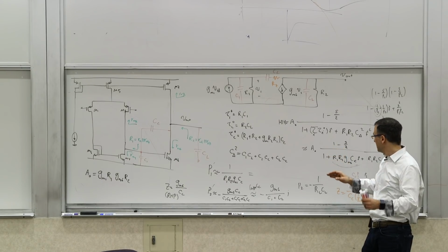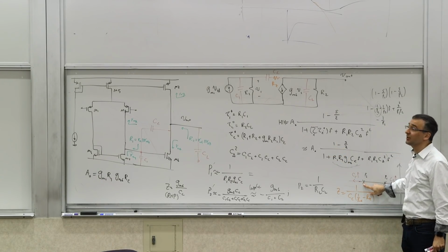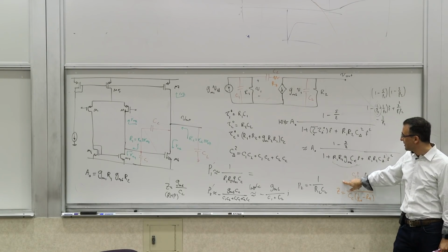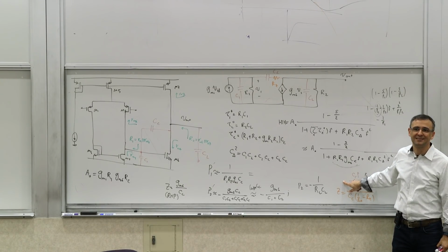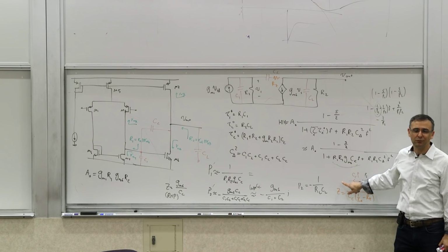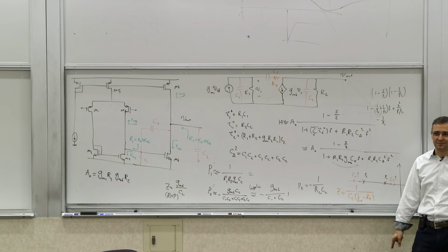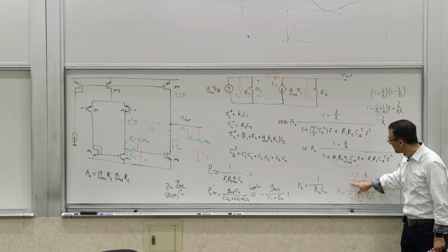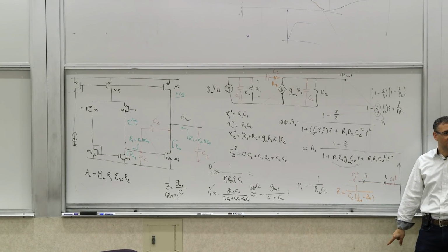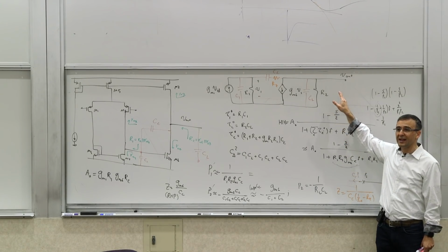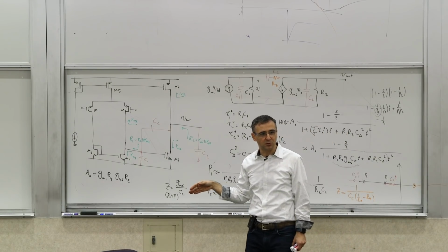In theory, at least, you can bring it back and put it on top of your P2, and then you're limited by P3, the next pole over. And that would determine your omega. Practically, you may not be able to push it this far out. But even if you can push it somehow close to this constellation of poles, it would reduce your phase, and it will start canceling the effect of some of your poles.